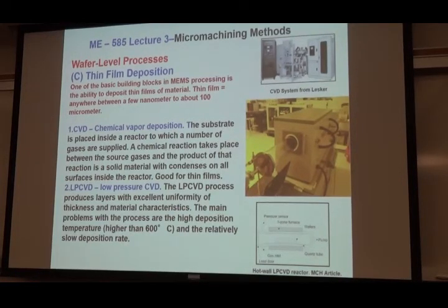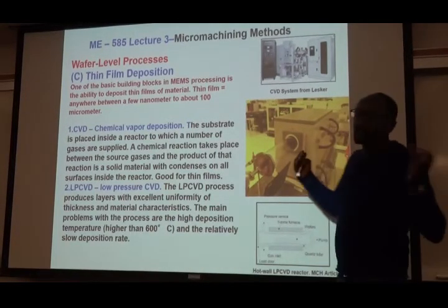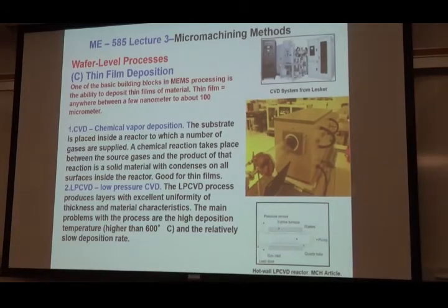So what you do is, again, take your wafer, already stuff is on it. Remember, in the semiconductor industry, we said you can do up to 25 to 35 layers. The MEMS about 8, 9 layers, so you're doing step by step. So far, you've done 2 or 3 layers. Now, you want to do a deposition of material. For example, platinum, gold, aluminum, silver, you know what have you. Okay, or some adhesion layer first.